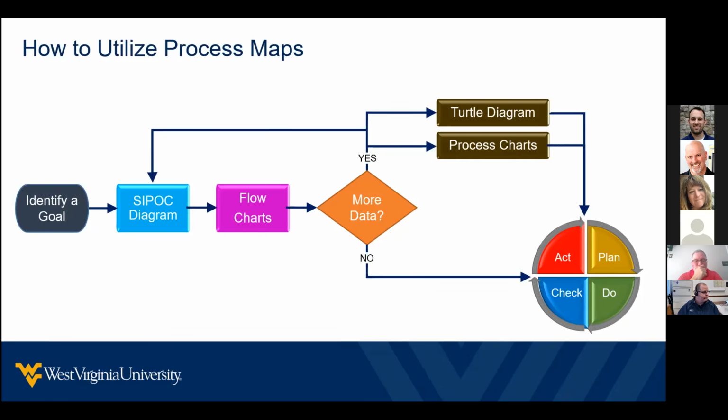As that flowchart is analyzed to look for the challenges and opportunities, it is not uncommon to come across a process step that is confusing or requires additional attention. You can certainly repeat the previous process to create a SIPOC and flowchart to further digest it, but you can always go a step deeper in using turtle diagrams or process charts to understand the process steps. A SIPOC or a turtle diagram provides high-level focus on inputs and outputs of a single process, including resources, team, process, and measure of success.